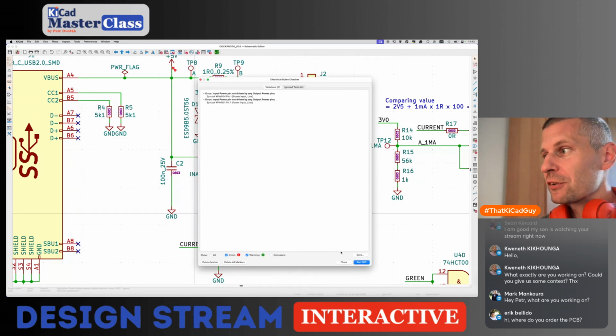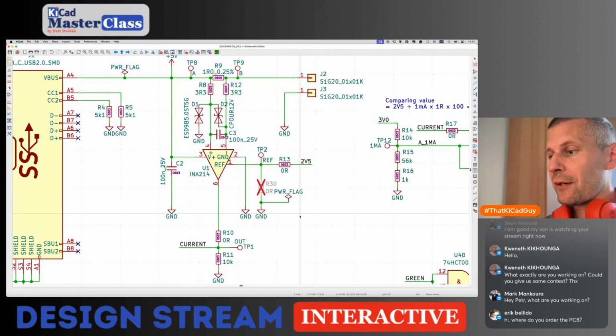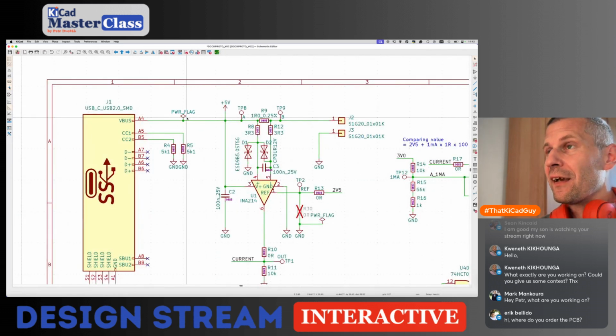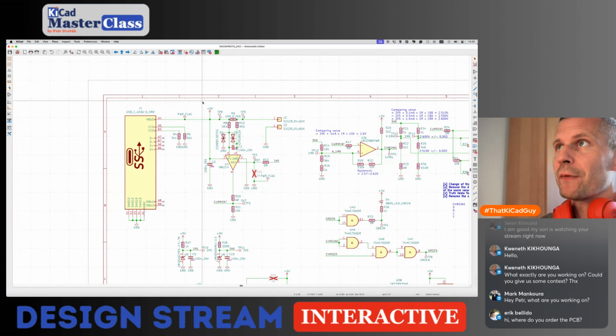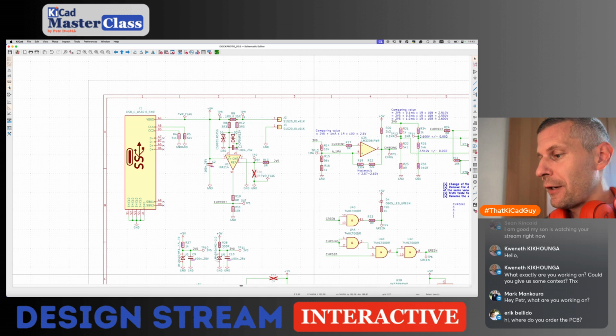It doesn't affect the function, it only affects the presence of errors. You can see that I added two power flag symbols and all the errors disappeared. It didn't change the function of the circuit, it didn't change anything. It only made the KiCad electrical rule check satisfied. So it's up to you. If you can live with such errors, waive them. If not, add the power flag symbols. I hope I have explained, and I hope you understood.